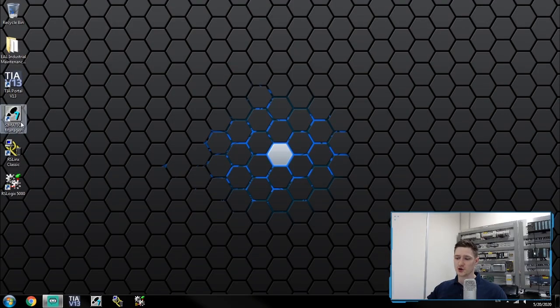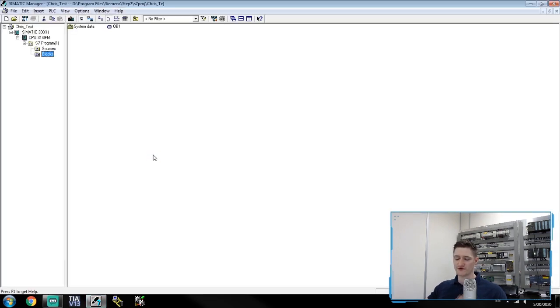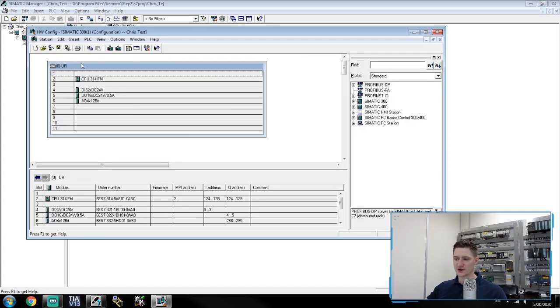So what we're going to do is open up SIMATIC Manager. And it'll open up with our last program from last week, which was our test program where we created a brand new project, created its hardware configuration, and then designed a very basic program. If I go to our SIMATIC 300 PLC and double click hardware, we should see our hardware configuration from our PLC, which was the CPU 314IFM. It had a 32-way input card, a 16-way output card, and a 4-way analog output card